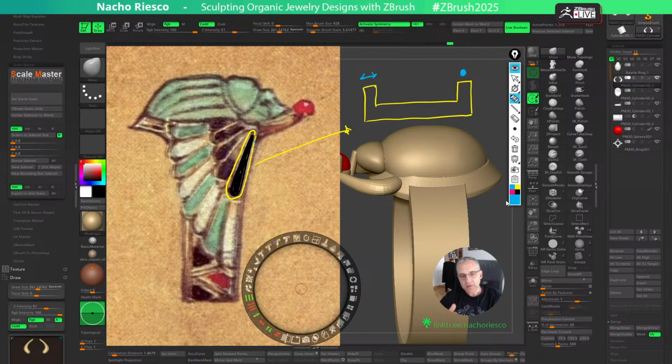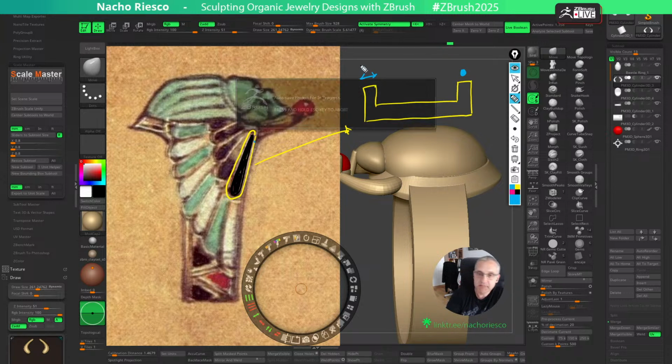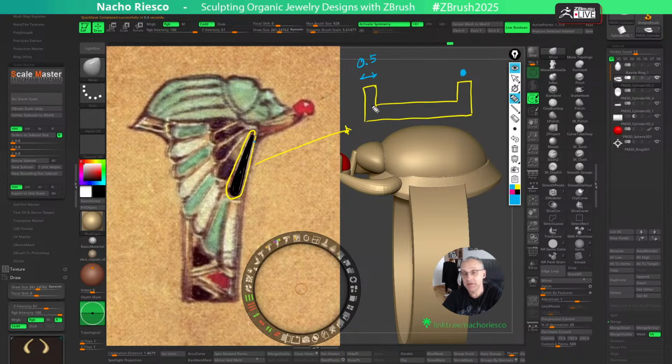But once we have the casted piece in metal, it needs to be sanded, filed, ground, and handled in many different ways until getting the final results. If we are talking about final distances, because you are asking about a thickness, we are trying to get maybe half of a millimeter here or even less.